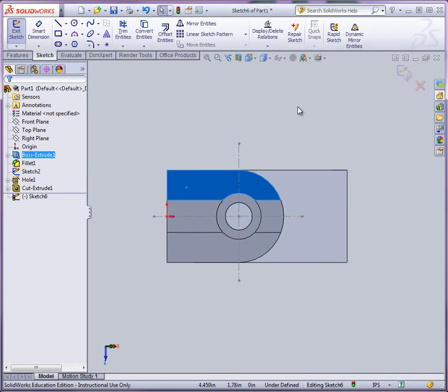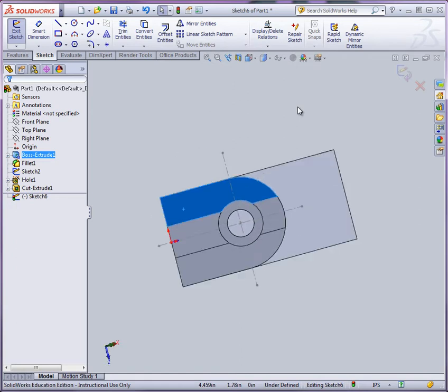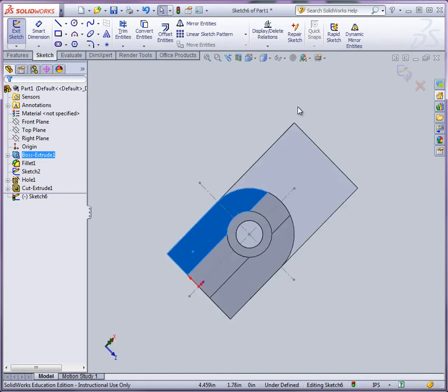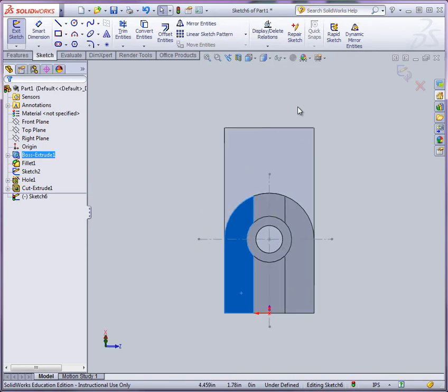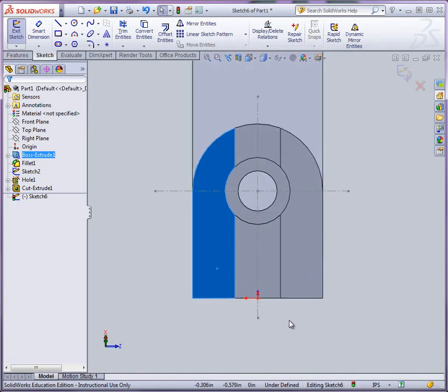Now look at this. If I want to rotate the view, I can use the Shift, Control, and Alt keys together with the arrow keys. If I do Alt and left arrow key or right arrow key, you can see how I'm rotating it with increments, okay? And this way you can rotate your view without rotating the model.